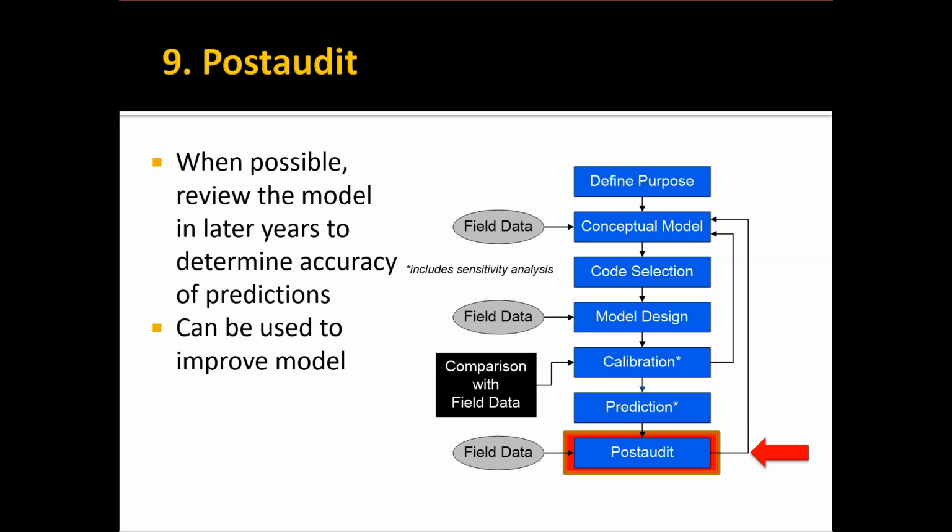Finally, if your model is part of a really important decision-making tool for a water agency, for example, it's useful to do a post-audit. A lot of times models are built and then used for years and years. Sometimes you'll tweak the model and update them, but if you can go back years later, or let's say you're using the model to predict some future event, well then, that event occurs. You can go back and say, well, how well did our model do? How accurate was it? And this information can be used to update and improve your model if you're going to continue to use it. Otherwise, maybe you just learn from that. Post-audits aren't always done, but it's a good practice as you go forward.